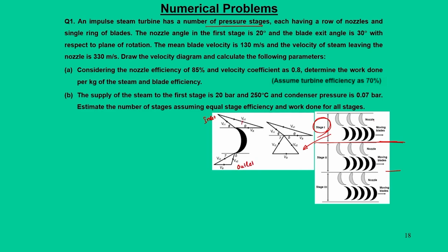So, for this we have the nozzle angle theta, the blade angle phi, then we have the fluid exit angle delta and the blade angle gamma. Before that, you have already understood what the inlet and outlet velocity triangles are. Now, to solve these problems we need to combine these two diagrams, drawing them with the same blade velocity Vb, combining the inlet and the outlet velocity triangles in a single diagram, which is going to look like this.